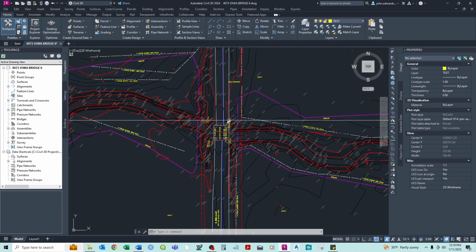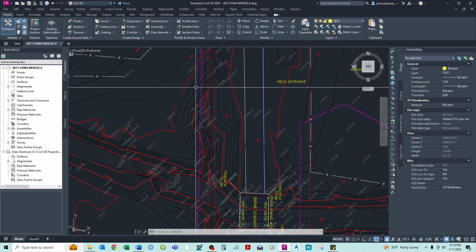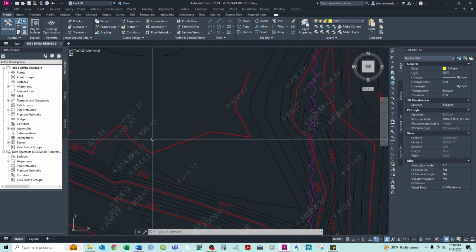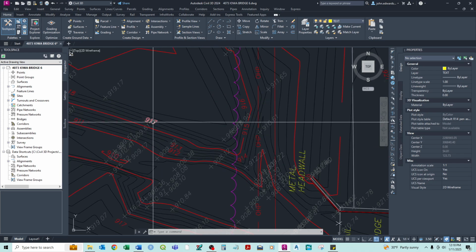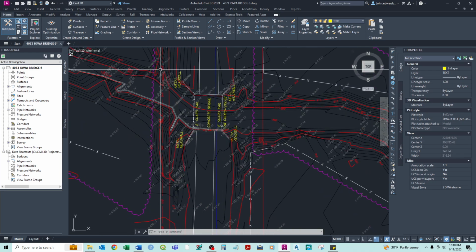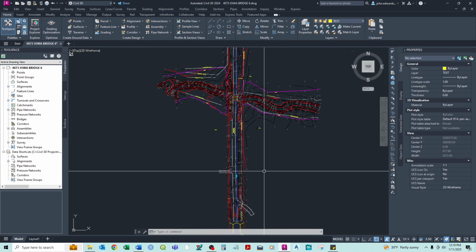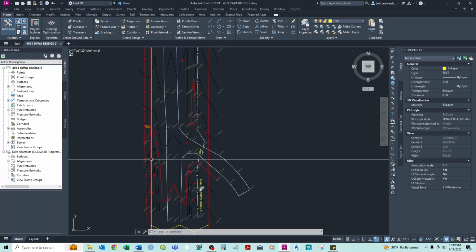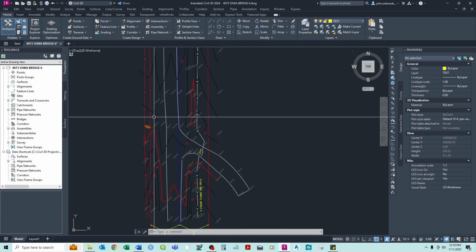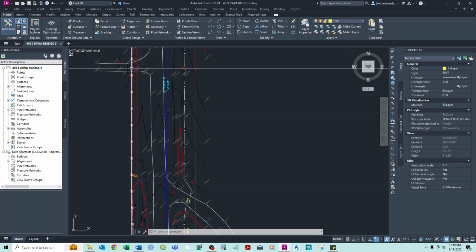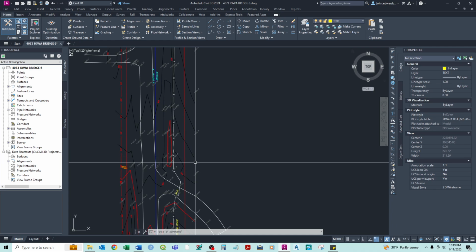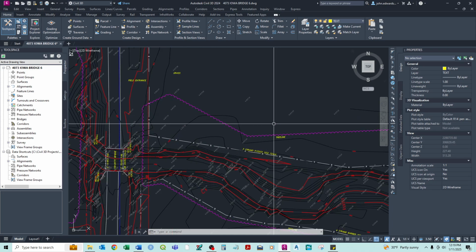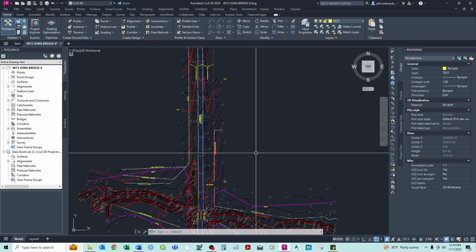And then we'll look through here. So here's all the 2D line work. He's got all the contours as 2D objects, polylines. We've got specific points they shot, the labels for all the contours, labels for the bridge, etc. Fence lines, normally edge of pavement, any utilities that they found. They're not doing GPR or anything to find these. It's just whatever they can find, either overhead or just sticking out of the ground. And normally you'll see the tree line. So that's our basic survey.